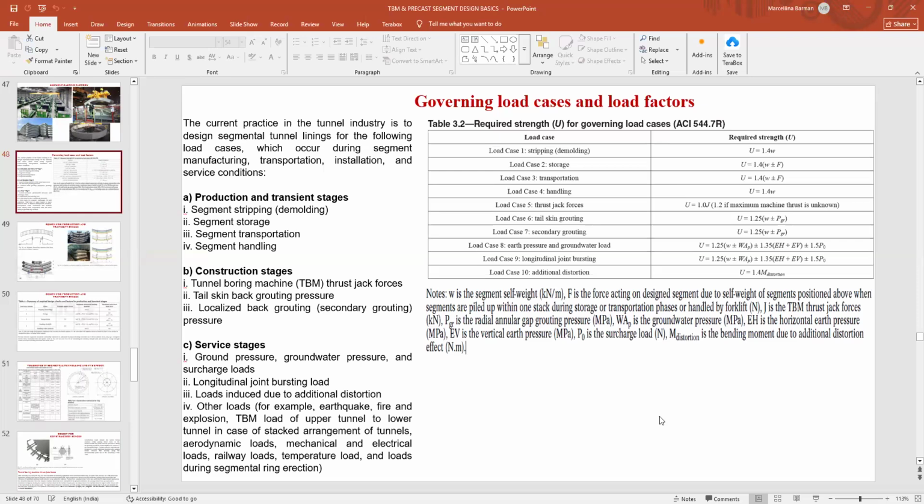Sir, same like Calcutta Metro under the Hooghly River, I think it was 300 something for the river part, and the rest part 275. I remember some discussion initially, but I am unable to recall that 300 millimeter below Ganga and the rest of the part 275. Yes, because that part you will have more aggressive conditions, because here you have the water, and for the durability also you increase the cover. So if you increase the thickness of the segment, that will also cover the durability part.